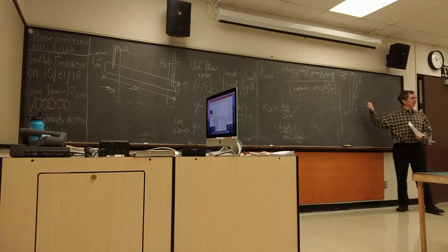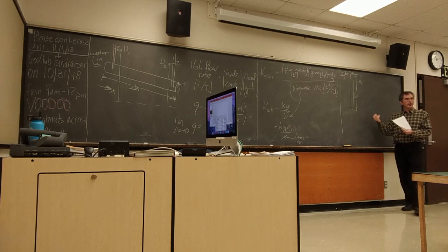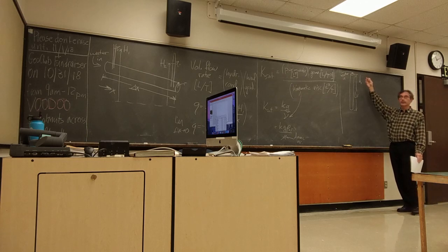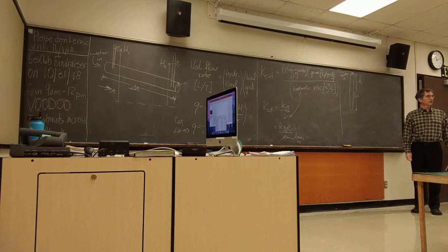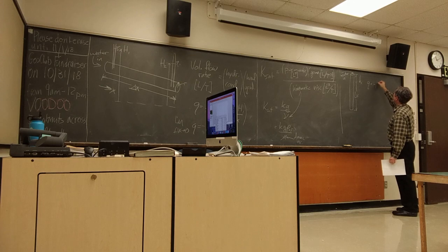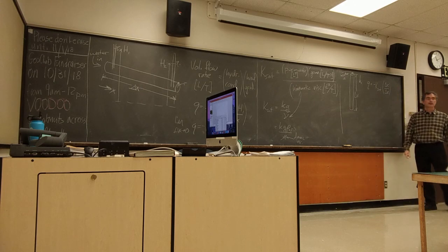All right, if I've got no water table, so no pressure, the head is just the elevation. Right, if head is pressure plus elevation, then I don't have any pressure. It's atmospheric pressure, which we, by convention, assign a value of 0. If pressure is 0, then my head is just the elevation. What's the difference in elevation then between the top and the bottom? Delta x. So here my volumetric flow rate is... the head gradient in gravitationally draining water is 1.